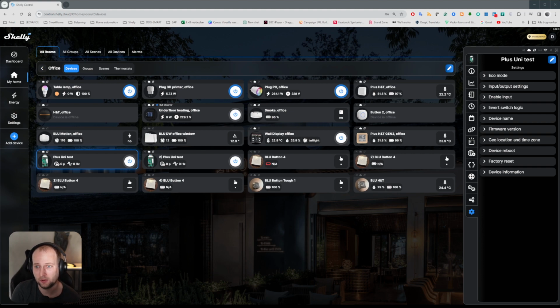Typically you only need a Shelly bypass if you are using the dimmer without the neutral. So the Shelly dimmer works without neutral. To work without neutral, you need at least 10 watt consumption. But if you have the neutral connected, you can go down and use it with like a 2 watt light bulb if you want to, and it will work in 90% of all cases.